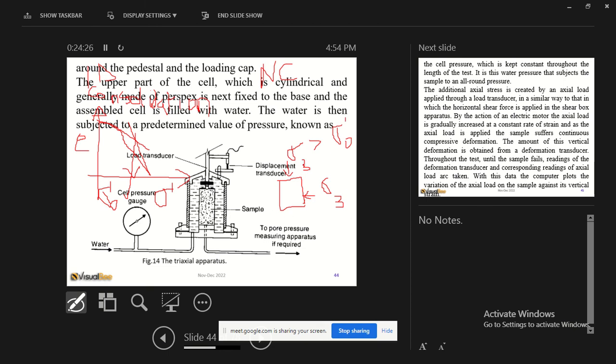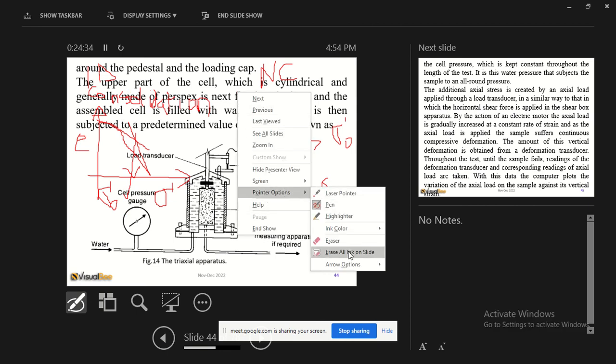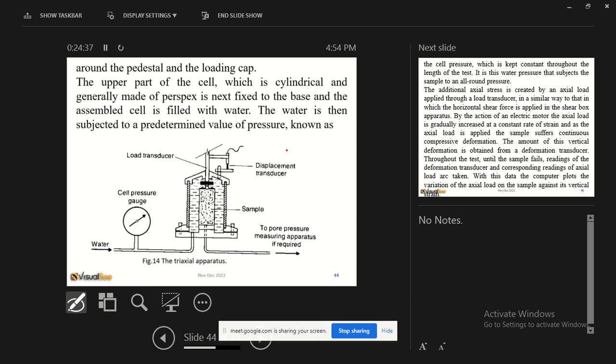So this consolidation stress has something to do with this pre-consolidation pressure. I don't think there's any other better way to say that. So having said that, you apply sigma 3, which should be higher than the pre-consolidation pressure. That's an all-round uniform stress for some time. That is to erase the memory and make it normally consolidated. After that, you apply something we call deviator stress, delta sigma.